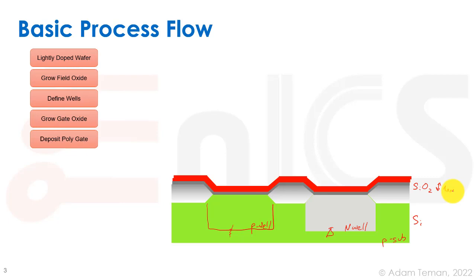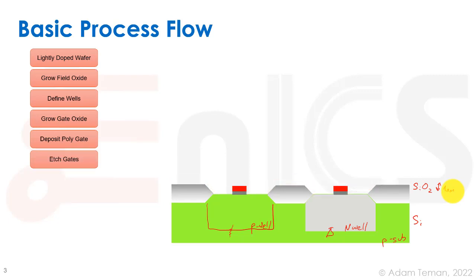And then we can bring in our mask and pattern where we want our gates to be. By then etching away the pattern, we can etch away both the polygate and the silicon dioxide, and we get this sandwich type of thing. So we have this self-alignment, which really defined our gate. We didn't have to have two different masks, because if one of the masks was patterned over here and one of them was over here, we'd have a bad overlap between them and some excess areas on the side. But because we did it together, we got this nice patterning.